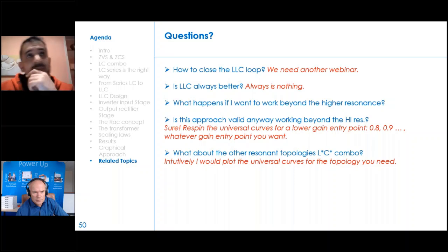First, fixed frequency converters are easier to manage and easier to parallel at the system level. The LLC converter is much more complicated to synchronize at system level. So use the LLC converter carefully. It is a very powerful converter, but it is much harder to synchronize.